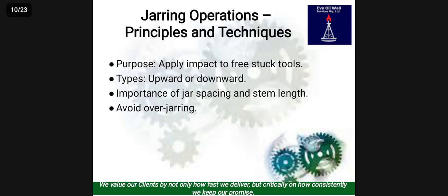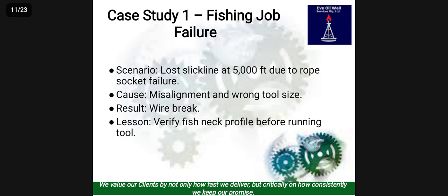Downward jars push down or latch. Proper jar spacing and stem length are crucial. Overjarring, that's just oil fish slang for how to break more than you fix. So be mindful of the way you jar to engage your fish.